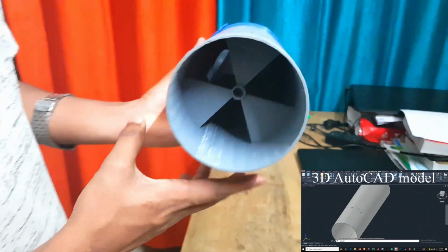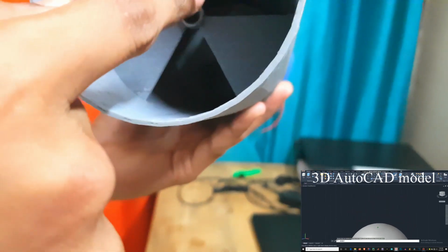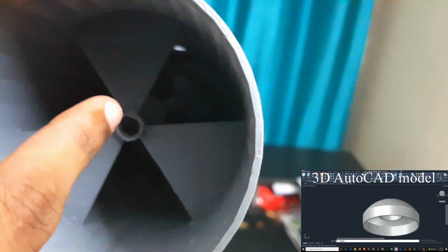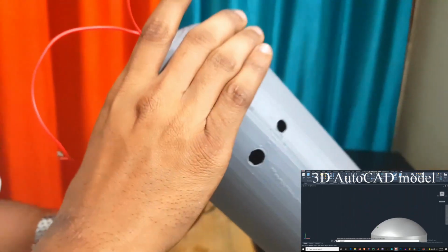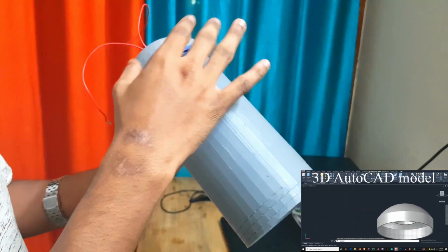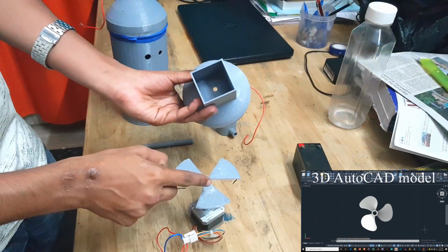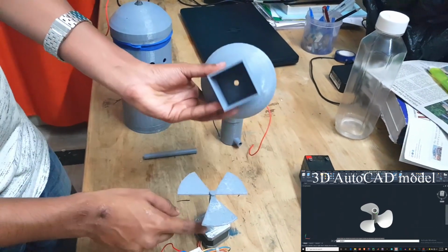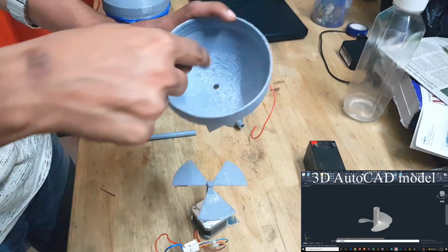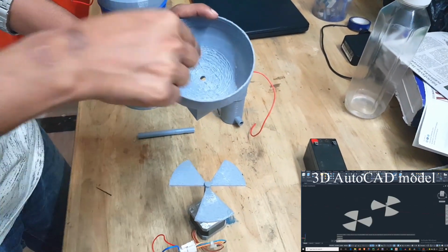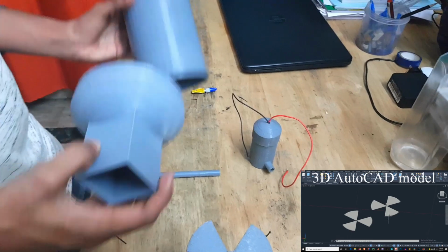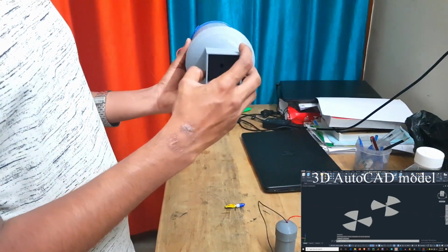So yeah, this is the main column and there is a fixed shutter inside this which doesn't allow microplastics to come through it. And if you can see over there, there is a rotor which creates centrifugation, and this is the other side of the cap which holds the gear motor to create centrifugation. And this is the cap, and this whole setup of stepper motor plus this mobile shutter goes inside this. The stepper motor fits into this and the shaft comes out through this hole, and this shutter also comes out through this hole, and this whole setup would be plugged in like this, and this would become our one single bot.